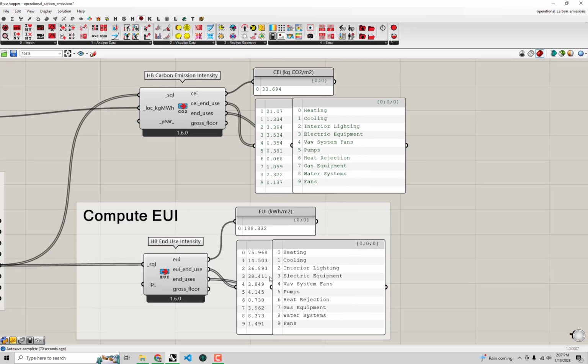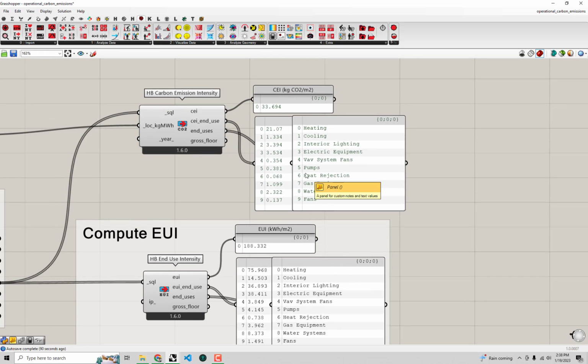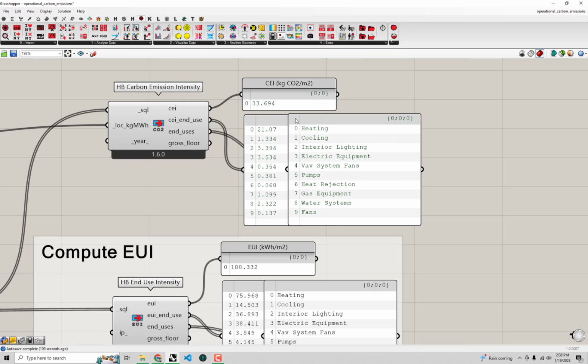Whereas if we were to try and focus on just reducing energy use, it might point us in a few different directions, like reducing heating, maybe also reducing lighting with some LEDs. But when we take a step back and look at carbon intensity from this perspective, if we want to pick the term that is going to be most impactful for reducing the greenhouse gas emissions of these buildings, by a long shot, it's heating. And probably we can reduce this a lot simply by swapping out those boiler systems with heat pump systems.